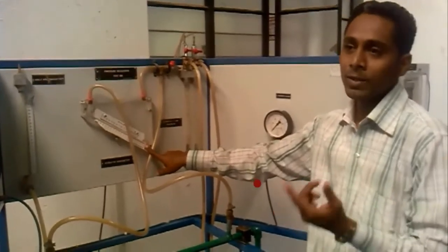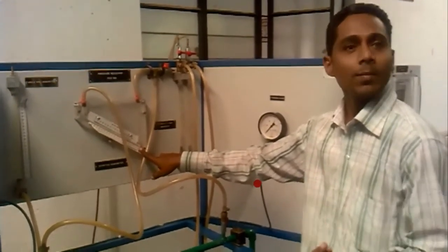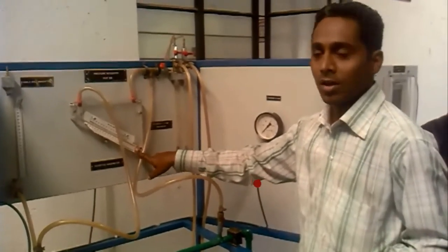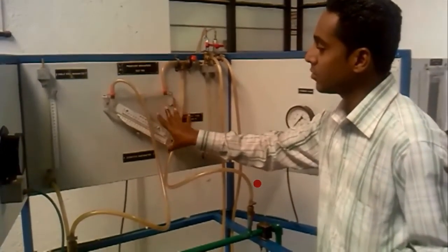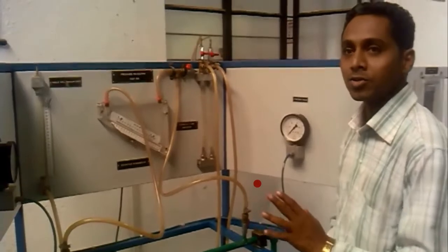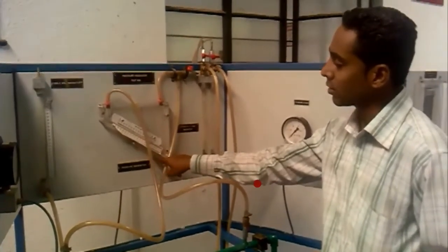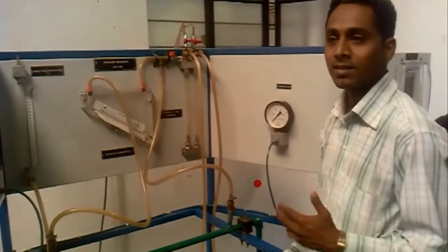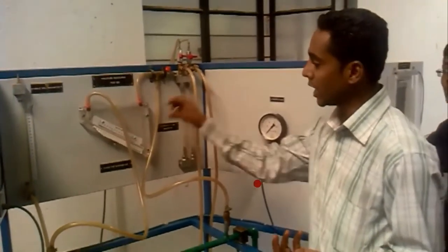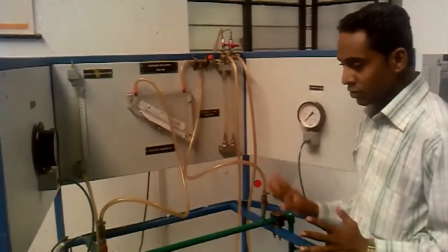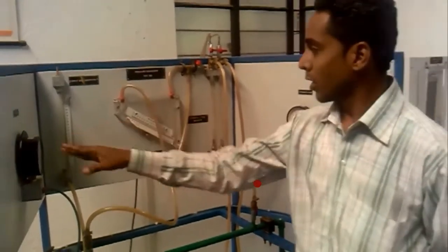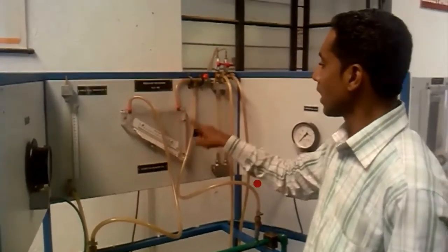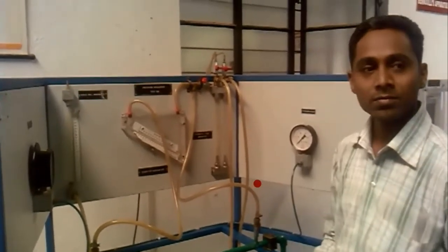Okay. So that rise in mercury level we can read on the scale, and that is L. L sin theta will be h, and rho g h will be P gauge, and P absolute will be P gauge plus atmospheric. In this way we use the sensitive inclined tube manometer. For this, the angle with horizontal is 30, so sin 30 will be 0.5. So L sin theta means L into 0.5 will be h. Understood? So in this way, pressure gauges, single well manometer, differential tube manometer, and inclined tube manometer.